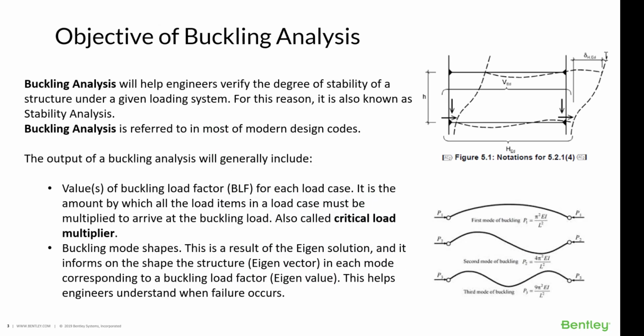Buckling is a very dangerous condition. The failure occurs suddenly as a structural collapse with little or no warning. Buckling analysis helps to check if the structure is stable under certain loading conditions. The buckling load factor is the main result that we're looking for when performing buckling analysis.